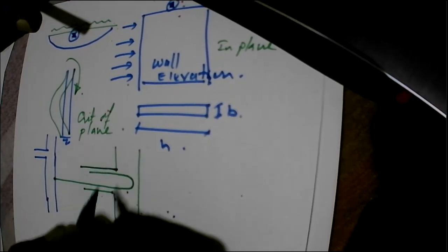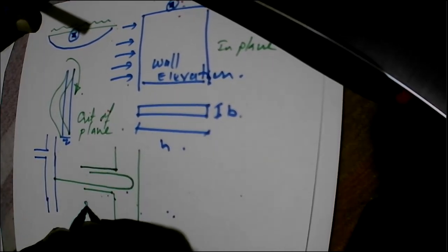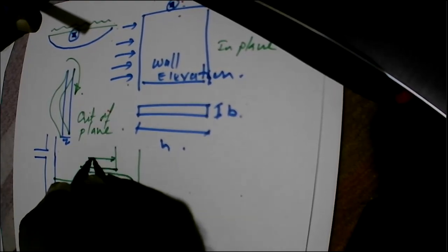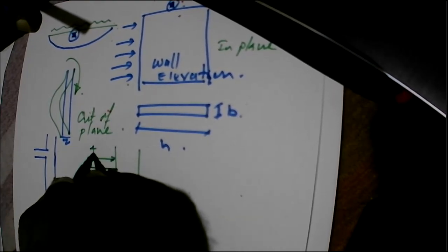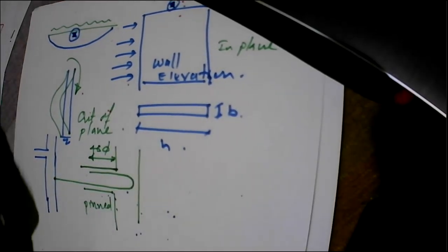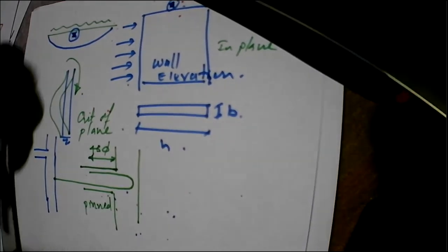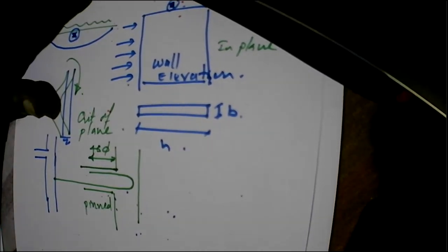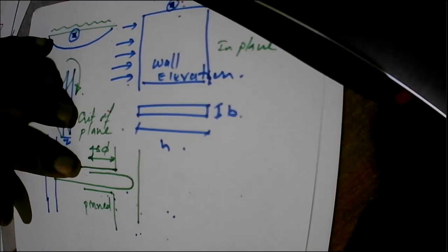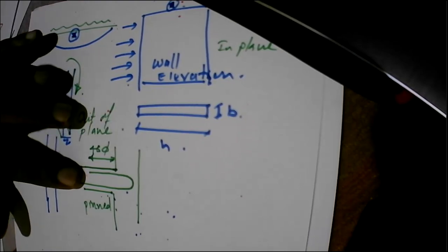But for the analysis of the slab, you will consider it as pinned. And general rule is we limit the length of the top bar only to about 45 times diameters from the face of the wall. So when you do this, there will not be sufficient anchorage length and continuity of reinforcement to generate a hogging moment here.